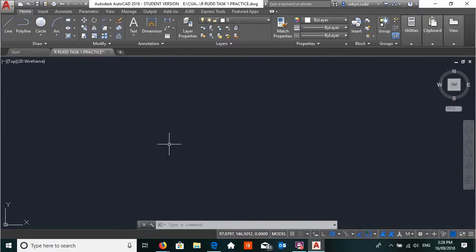So before we start drawing, we really want to get into the practice of identifying that this is our drawing area, because I said it is infinity. You could be drawing a drawing up here, and you could be drawing a drawing somewhere way up here, or you're zooming in and out and you just don't know where your drawing is, and it can be quite confusing. So you want to create a limitation or a drawing area that prevents losing your drawing. So you're going to be creating an invisible rectangular space. All right. So I would set this up, and that is called limits. So we're going to type in that word. So I'm going to just go down here, and I'm going to click onto my little command line down here, and I'm going to type limits. All right. So LIM.